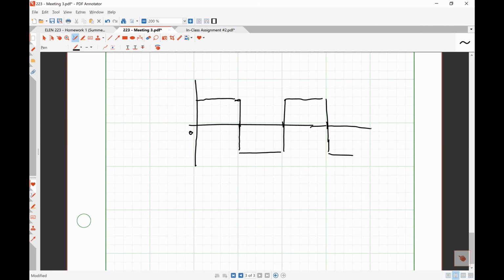And when we deal with op-amp circuits, we're going to talk about how they can be used to integrate and differentiate signals. So if you can produce a square wave and integrate that, you get a triangular wave. Or similarly, if you can produce a triangular wave and you differentiate that, you get a square wave. Oh, okay. That's really cool. Yeah, so it's just a couple of components.